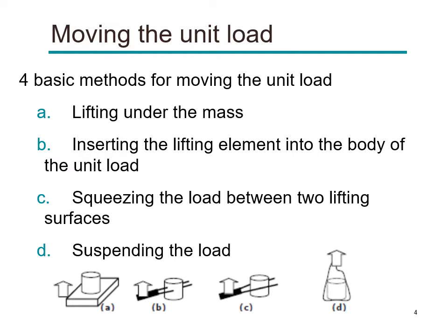And the fourth method is suspending the loads. For example, if you have a jib crane, hoist, or a bridge crane, you can suspend the item using such chains or cables, and then using a hook, you can lift them up and transport. Okay, these are the 4 common methods of moving the unit load.